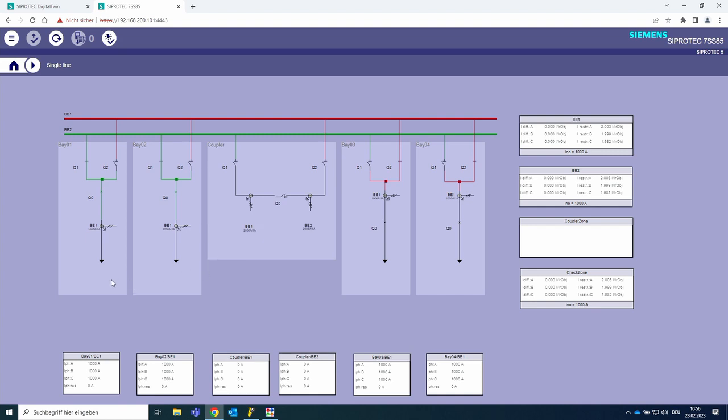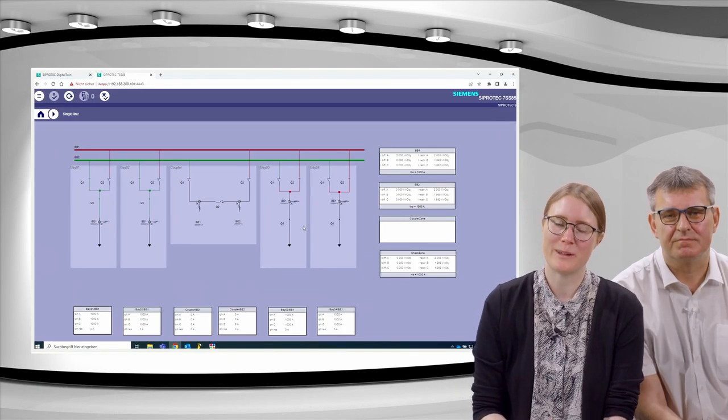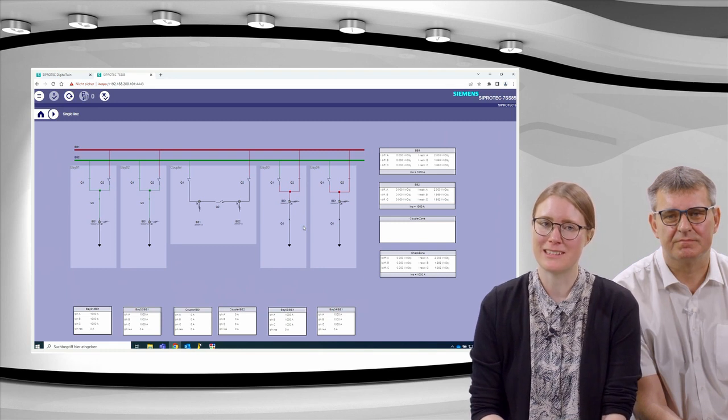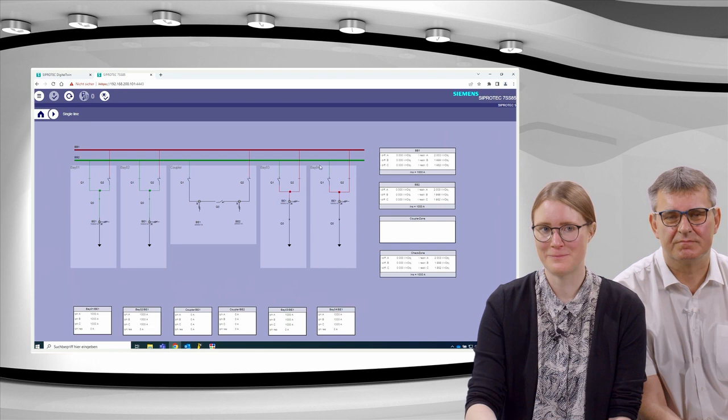And now the current would be flowing like this, so towards the busbar 2 in bay 1 and away from busbar 2 in bay 2 and the same for bay 3 and bay 4. So you can keep these two stable conditions a little bit in mind, because these conditions are always the pre-fault conditions in the test cases I demonstrate later.